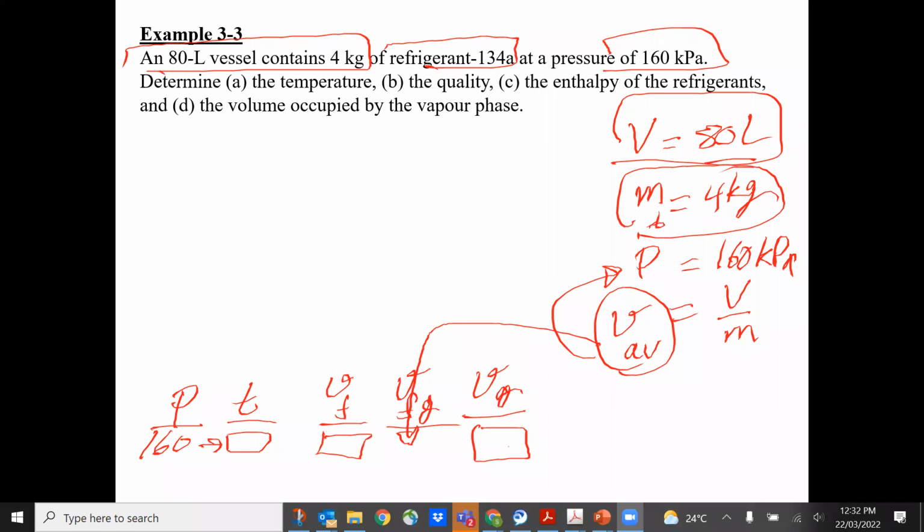Yep. And this is what you're going to find very soon. So if it's there, then the pressure is P saturation, and the temperature I can find easily because next to it is the temperature, and all other values I can find because now it's in the two-phase region. Okay?